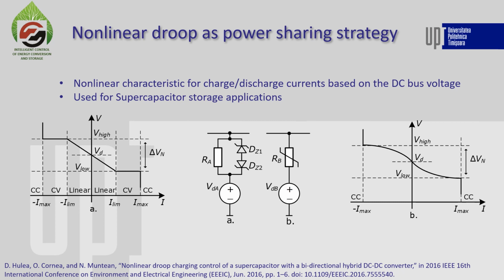As shown, above certain limits the converter operates in constant current mode, but within them it behaves as dictated by the mathematical function. For this purpose, the power function or the arctangent function can be implemented. Because trigonometric functions are widely used, some microcontrollers have a hardware implementation of them, for example, the C2000 family of Texas Instruments.